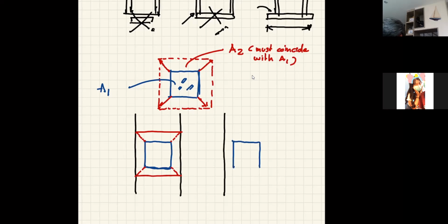If I have a steel plate like this, but this time the concrete is wider on this side, what do you think the area of the concrete A2 would be? Again, we go with the same distribution. So it's 45 degrees out here, 45 degrees out there, 45 degrees out here, and 45 degrees out there.